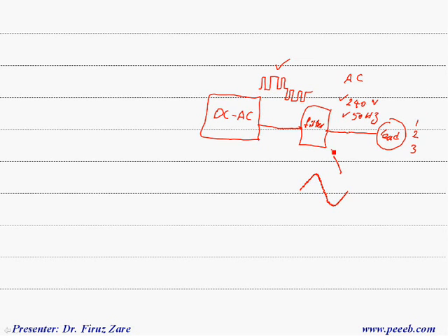So in this case we have a DC voltage coming from other sources, for example PV, wind turbine and battery, and in this case we need to generate a regulated DC voltage, for example at 400 volts, suitable for this main DC to AC converter.